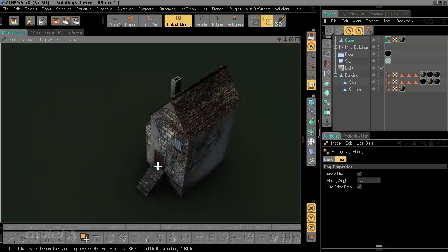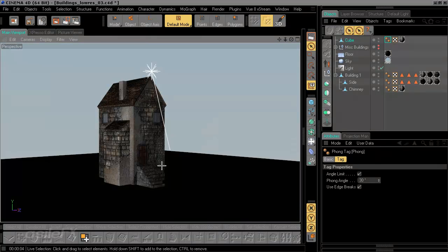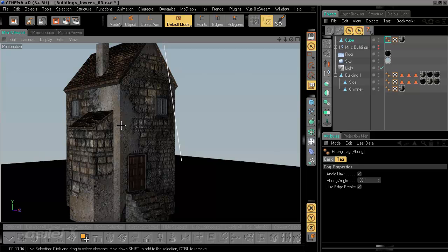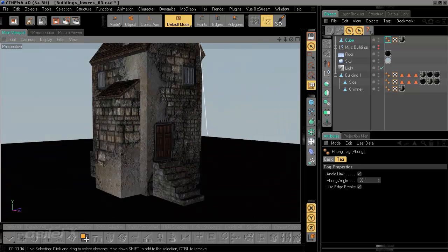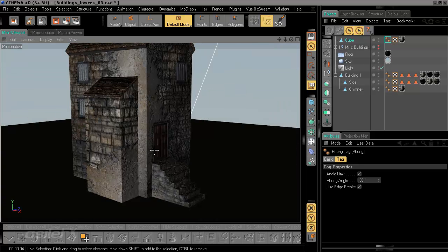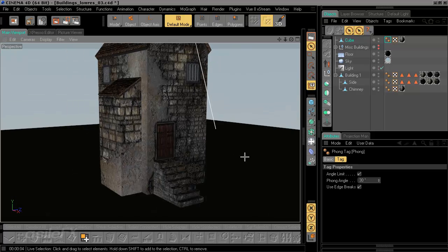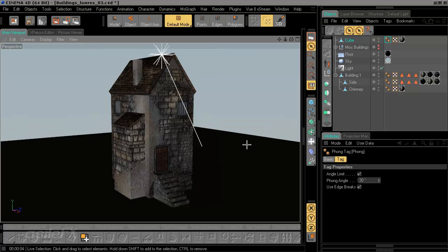But looking at it from the side over here, we can see that little edge showing up and getting highlighted. So we could do that for the top for the chimney as well, or even the wall and the different walls on the main model, using that UV edge and adding another normal or manipulating the first normal to create those nice fine lines, and that way we don't have to add any more geometry.